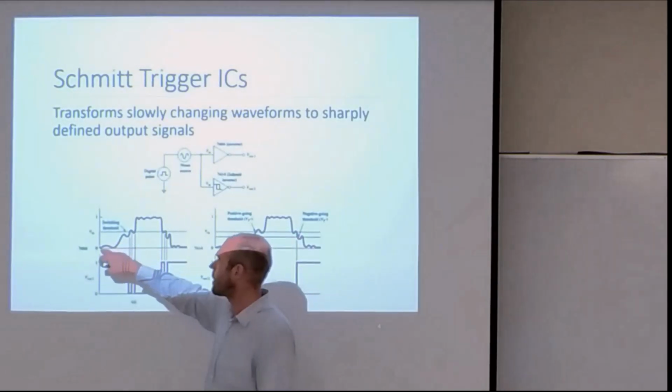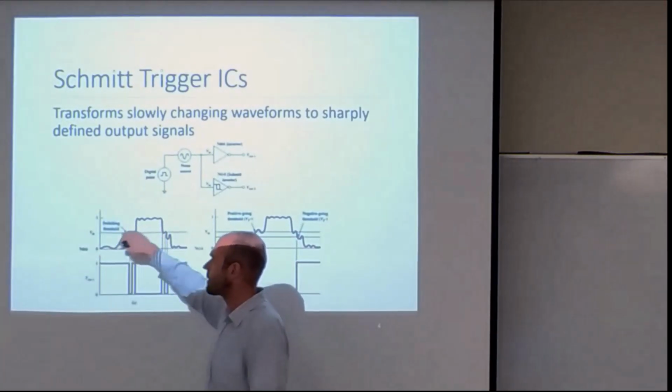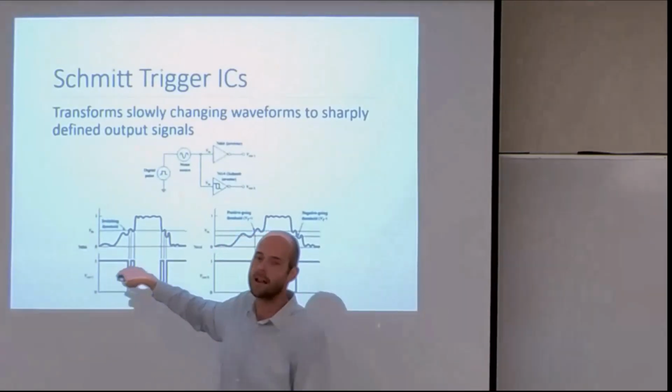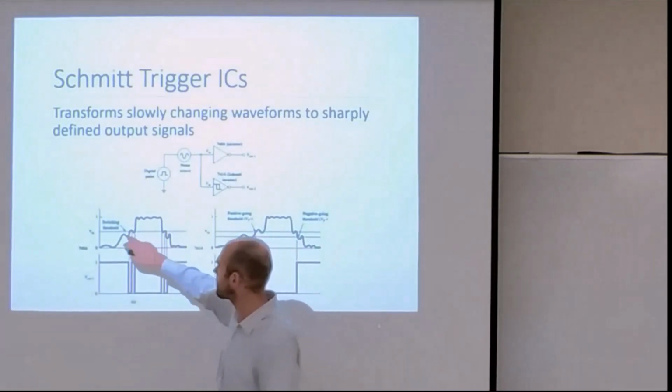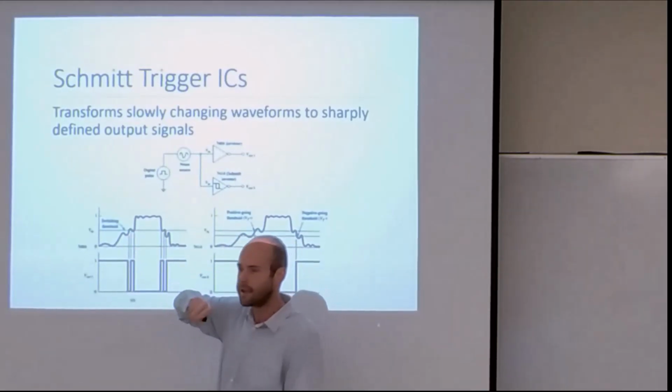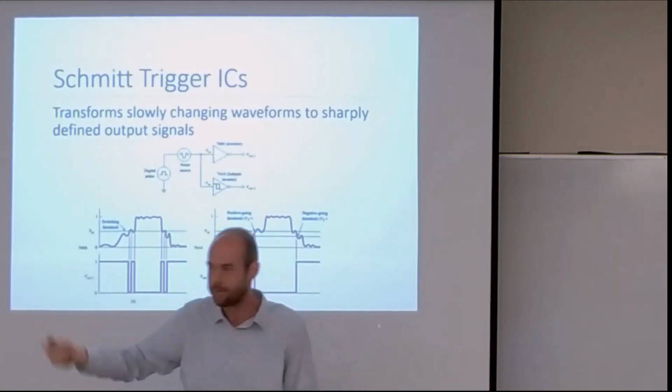So noisy signals give a standard inverter spikes high and low, something that looks like switch bouncing, just from crossing above and below the threshold.